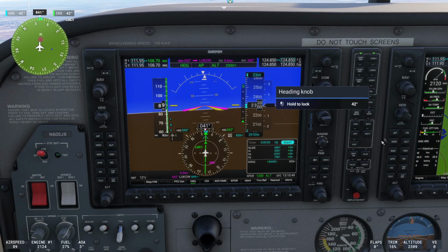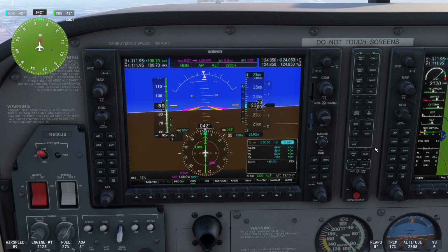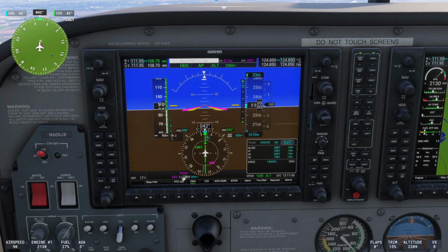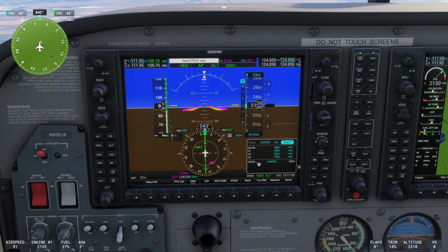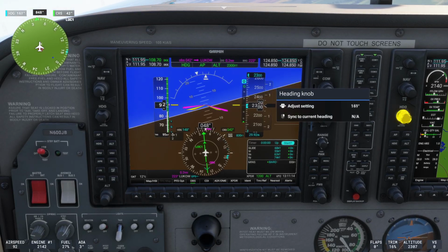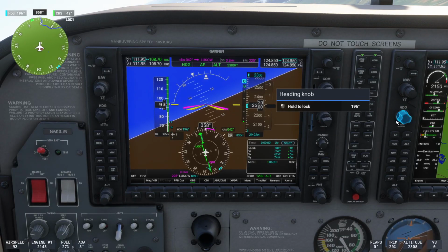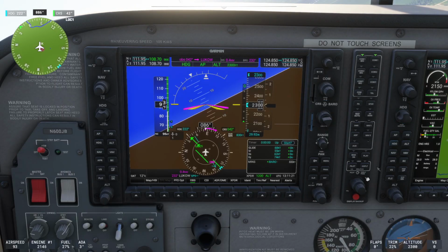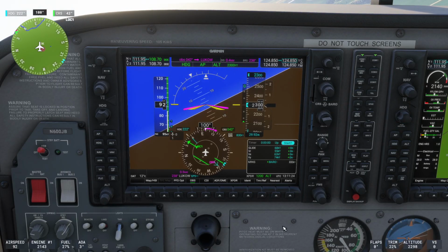And after proceeding through the parallel entry and coming back towards Lookout on the inbound leg, we can see that our distances start to close. We're at 0.4 miles out now. The outer marker is starting to go out, as well as this blue RMI needle is going to want to start flipping around. Now again, because we have OBS mode enabled, it's not going to sequence the next waypoint in the flight plan. So it's just going to continue navigating us towards Lookout, getting us distance information for that. And yeah, it's not going to mess our hold up or anything like that. Just like that, we have entered the hold at Lookout off the missed approach.